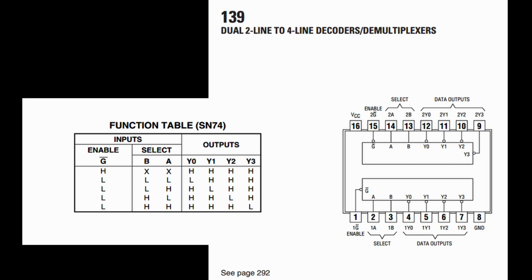This type of chip is often used for address decoding to select a certain bank of memory by the CPU. We'll see more about that in later videos. For now, all this chip is doing is creating a loading trigger for that LS166 that we talked about. I'll show you the logic traces of that chip later to understand what it's looking like.